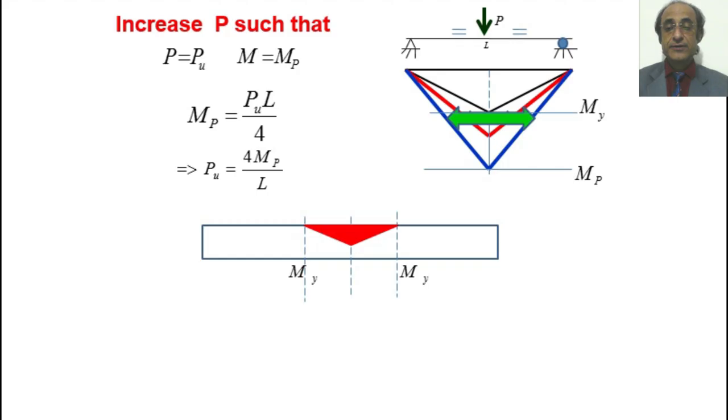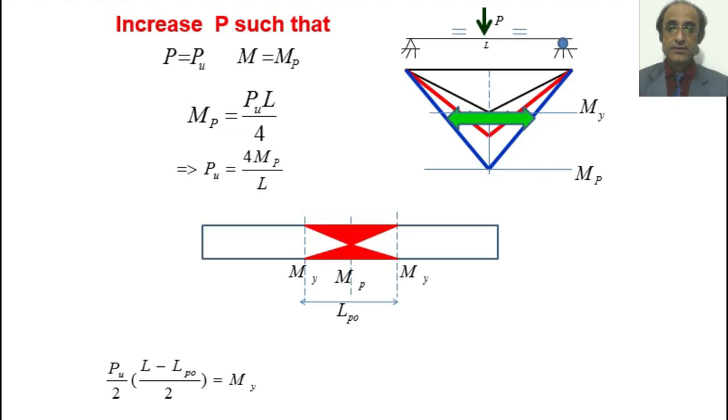And now here the two plastic regions are just meeting at one point. So at the midpoint of the section we have a fully plastic section, but it's not there as we go away from the midpoint. If we go away from the midpoint, we come across the region where the moment is equal to just the yield moment, and further away from these points on both sides we have the sections still in the linearly elastic range.